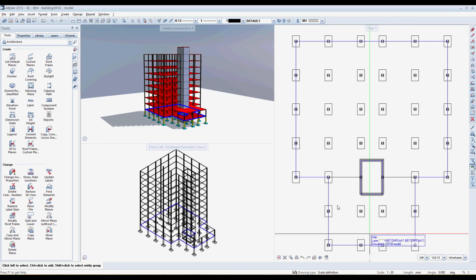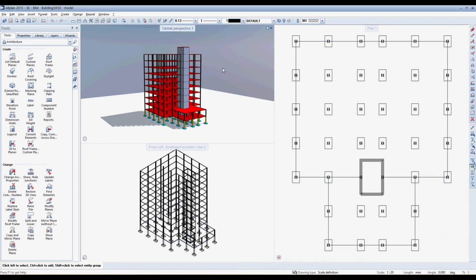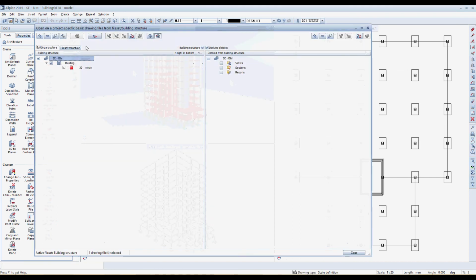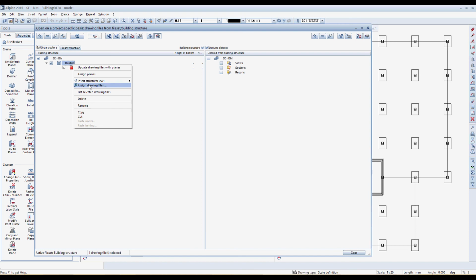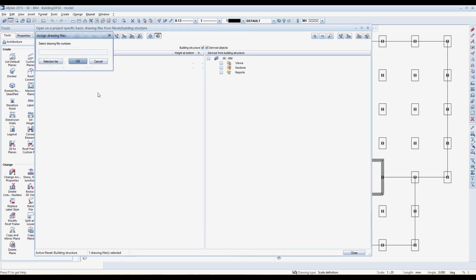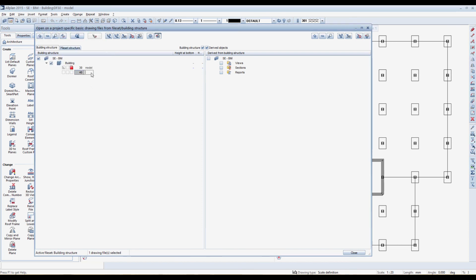So in our final step, we're going to import the EFC file again in Allplan. So first of all, we're going to create a separate layer for the reinforcement. So we're just going to import the reinforcement into the existing model in Allplan. So I'm going to create a new structure. This new structure will have the number 40 and I will call it rebar. It's something specially foreseen to store reinforcement.